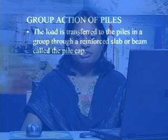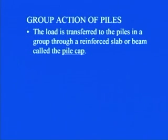The load is transferred to the piles in a group through a reinforced slab or beam called the pile cap. It is not that, as I showed you when I was sharing some of the pictures that I took from one particular site, the piles act as separate units. All of them have to act, or resist the load, as one particular unit. That is what we call group action of the piles.